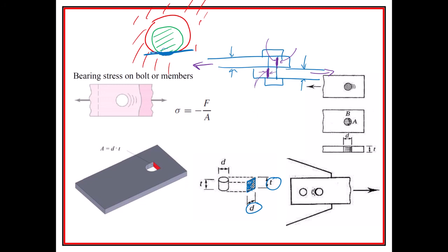So you get to find the stress, and then you have to make sure that you're using the correct strengths to make that comparison. And you could think of this as trying to lengthen the hole. I think that's the way that I best understand it. They show it as little wrinkles or something going on here. But you can think of it as trying to make the hole bigger, or trying to put a dent into the side of the hole. Now the hole used to be a circle. Now it's a little bit more of an oval, right? And the bolt used to have a nice clean face, but maybe we've put an indentation onto it, right? Here we've taken it and moved it out of shape.